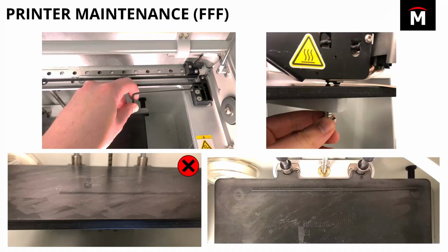You also want to make sure that purge lines are being printed. So on a Bowden tube system, especially if you're printing with hygroscopic materials, which are materials that absorb moisture from the atmosphere and the environment, you want to make sure you're running those purge lines, because what it's doing is purging and exhausting any compromised material. And that way, when you actually go to print your physical part, you're using uncompromised material.